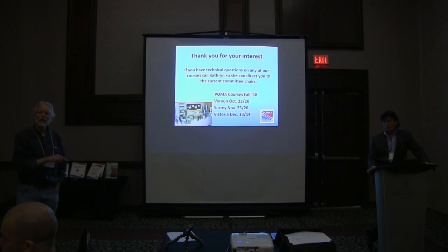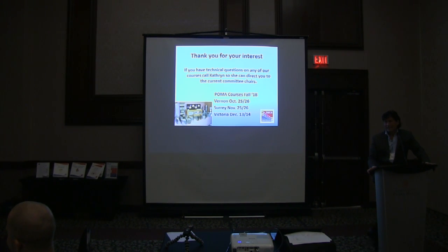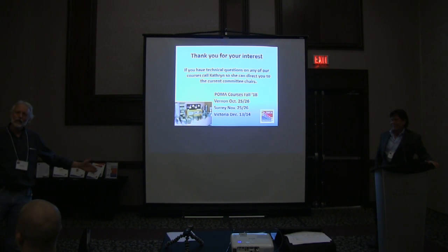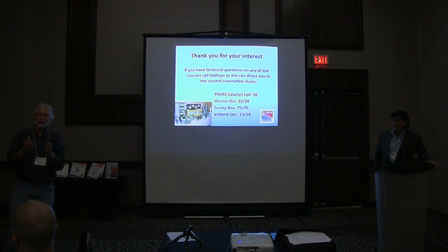We can do it all in math in 2 minutes. You don't need to study that. The fan laws answer all those questions. You have to just measure the existing system. You say to yourself, I want to add 0.2 of an inch for a higher MERV filter, and you can translate that into runtime per year in exact dollars and cents. It's very, very simple.